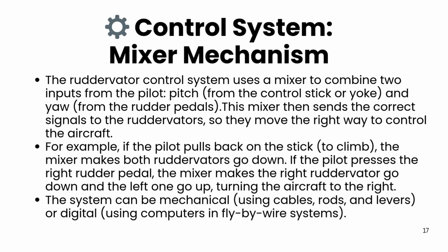So, both ruddervators and canards are part of the primary control system because they directly control the aircraft's attitude, especially pitch and yaw. Ruddervators control pitch and yaw by combining two traditional surfaces into one. Canards control pitch and can also improve lift and prevent stalls.